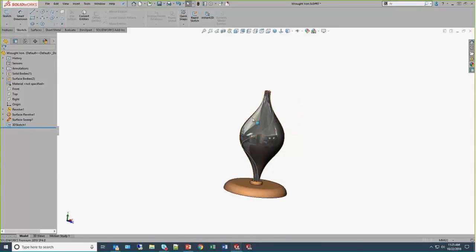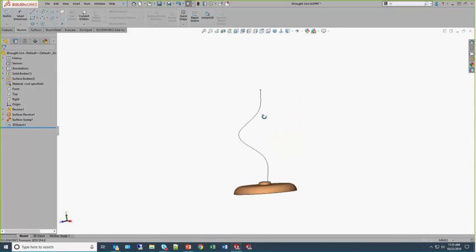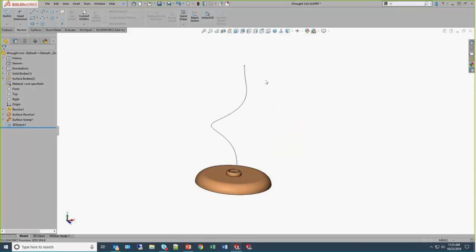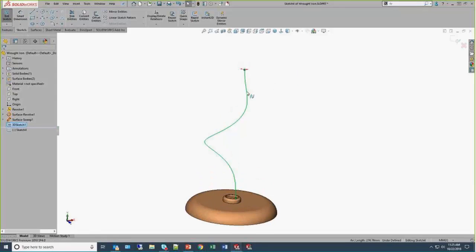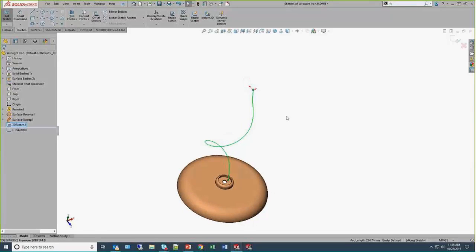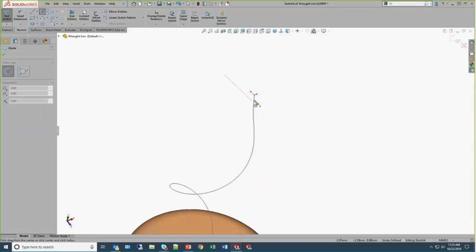And we'll just do a real quick tab to hide, and there we can see the shape of that curve. Now, even though it's not necessary in SOLIDWORKS anymore because we can directly create circular profile sweeps, I'm going to select that curve, hit the S key, and I've got Insert Sketch. And there we can see my sketching origin is right at the end of the curve. So behind the scenes, SOLIDWORKS is making a plane normal to the end of the curve, and I could go ahead and draw in maybe a little circular profile there.